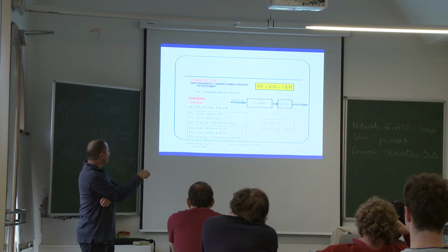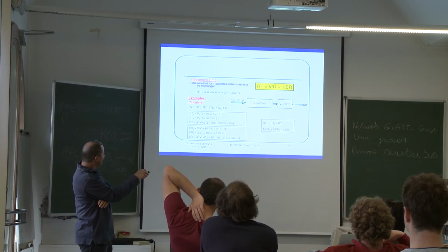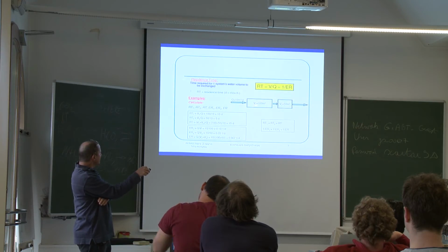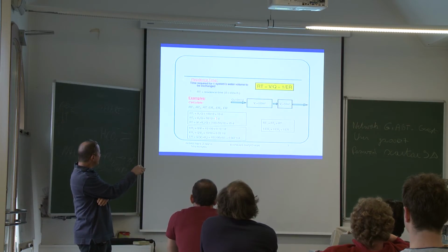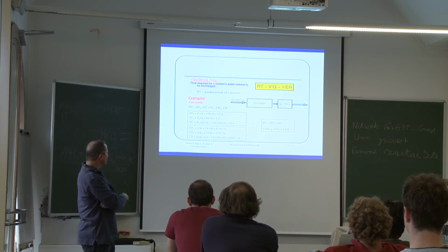So it'd be 10 days for this tank, 5 days for this tank, because 50 divided by 10, and the overall retention time would be 15 days, okay?